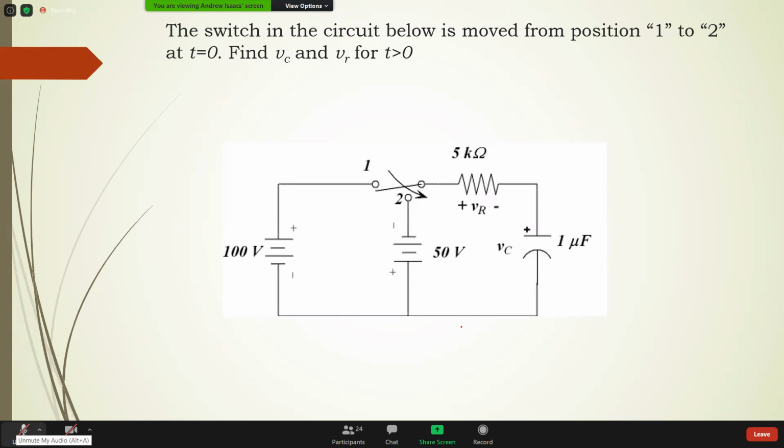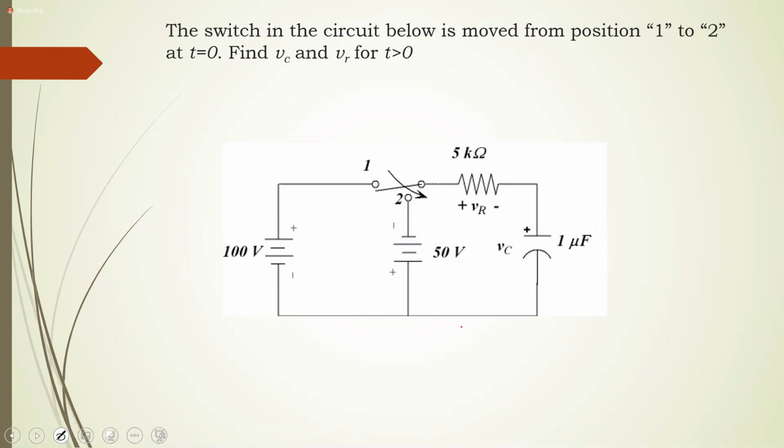100 volts. Do not change it. But you have a resistor, sir. It doesn't matter. Remember, the resistor is only dictating the rate at which the capacitor gets charged. But ultimately, it will be fully charged by whatever voltage is connected to it.